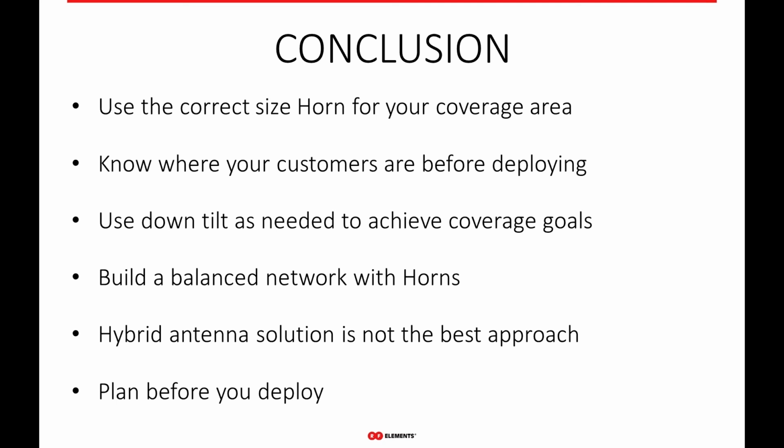Using down tilt as needed to actually achieve your goal, right? So again, understanding the relationship of how gain drops off as you tilt the antenna down is really important. And we have a link calculator on our website to help you figure that out as well. So using down tilt where it's needed, don't intentionally use too much down tilt because you're trying to deafen it as much as possible at the horizon. Use the amount of down tilt that's needed to make your link budget. So understanding that is really important before you migrate to horn antennas.